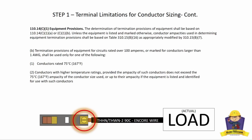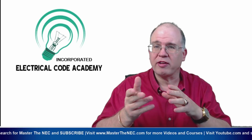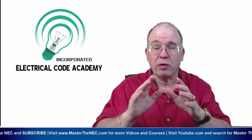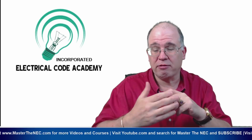Okay, so taking it back to me, I can use a 90 degrees C and apply my adjustment and corrections as long as I don't exceed the value that's in the 75 degrees C, because that's the terminal limitation. I'm perfectly okay. If the terminals happen to be rated for 90, and there's some cases where it might be, then I can use the 90 degree ratings.